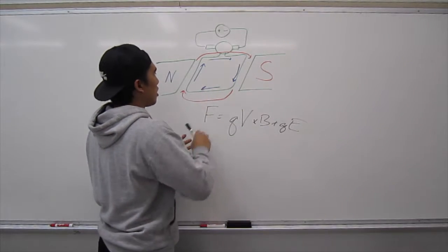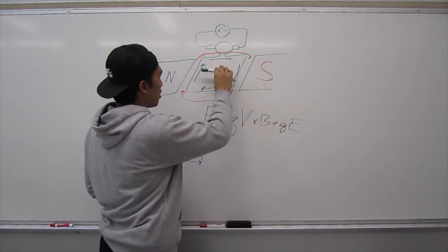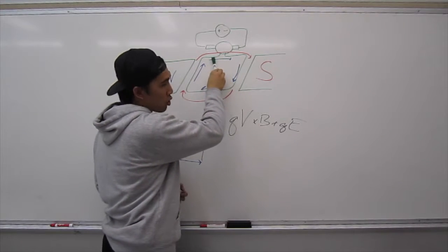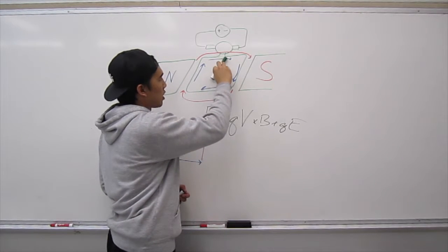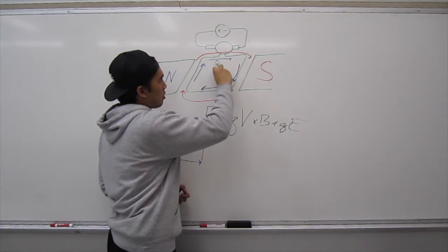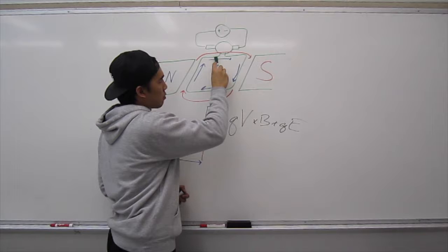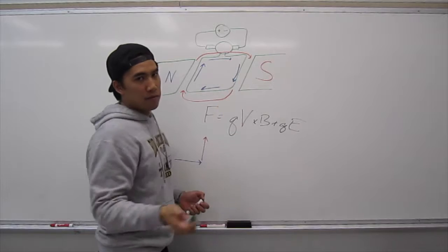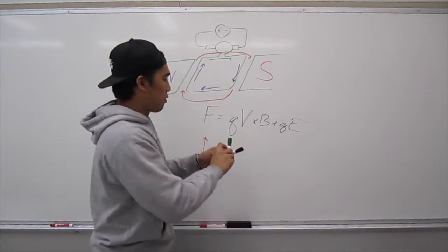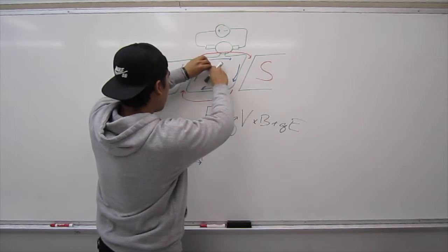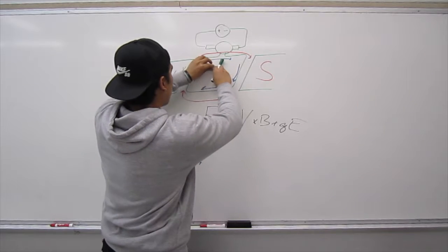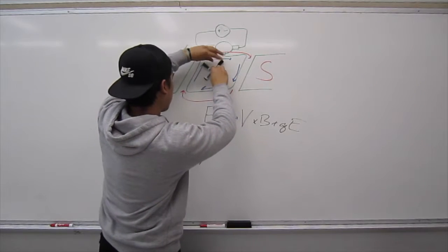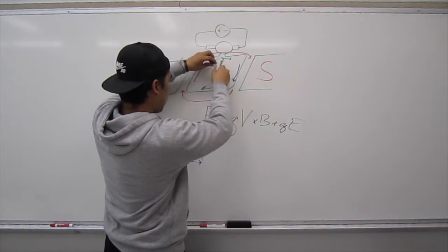When the coil here is turning, the second it's perpendicular to the magnetic field, the torque almost becomes 0. So essentially it's behaving like this. Slow, then fast, and as it reaches 90 degrees, slow, then fast, and slow, and fast, and slow. So the easy fix is just to add more coils, therefore we're going to get more rotation, and we'll never have to reach that torque of 0, since it's always going to be rotating. There's always going to be a coil rotating in its place.